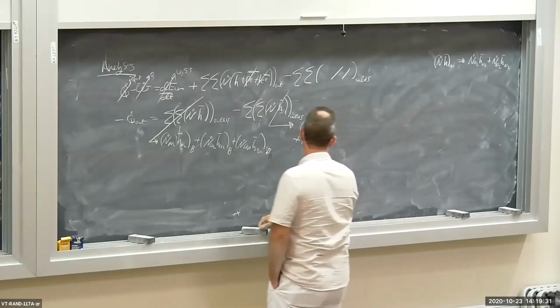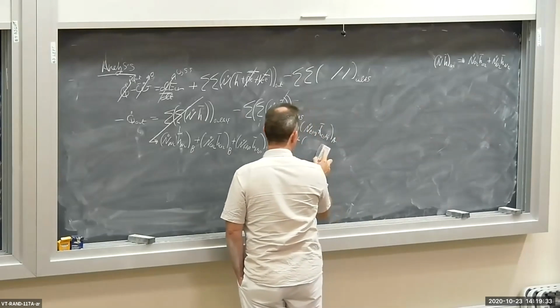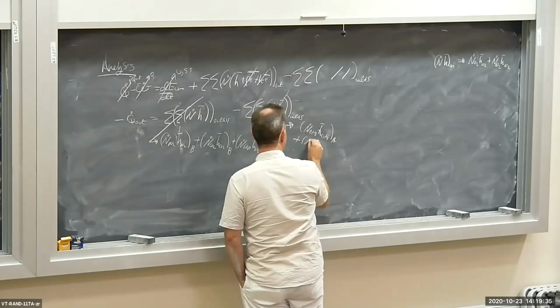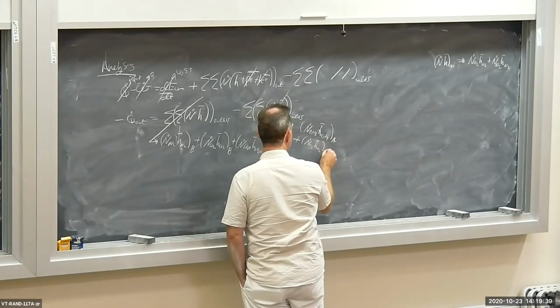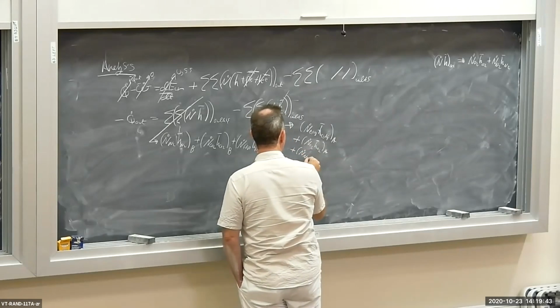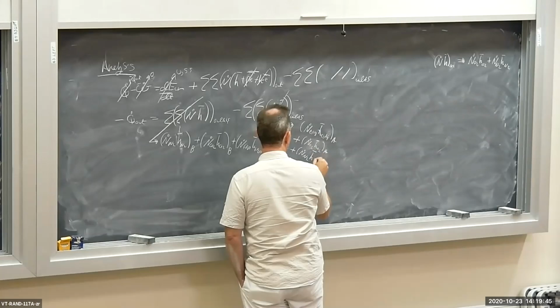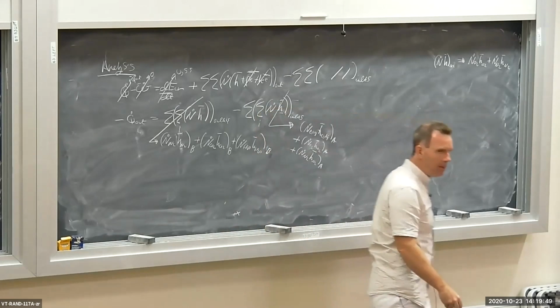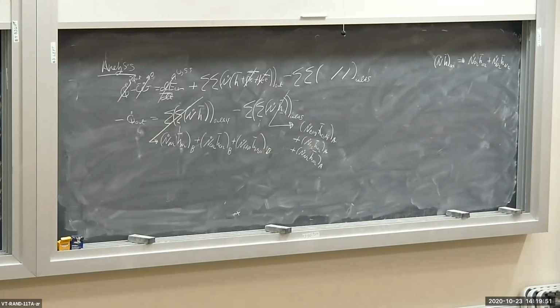So I'm going to write here plus N dot O2 H bar O2 at the inlet plus N dot N2 H bar N2 at the inlet. Okay, so I'm going to expand out the N dot H bar air term into the individual chemical components.